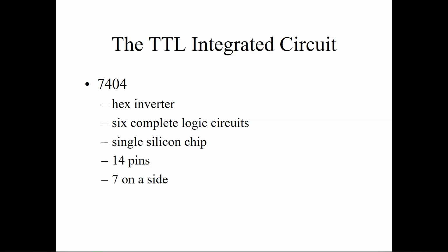It has 14 pins and 7 on each side. Pin 7 and pin 14 are your voltage and your ground, respectively. The other pins give you 6 different circuits to play with.